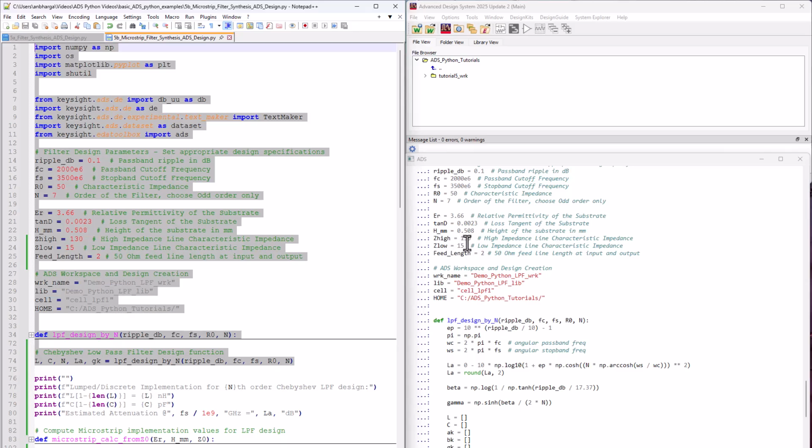So these two will put a constraint on what is the maximum inductance you can obtain, what is the maximum capacitance you can obtain, and based on that the length of the section will be determined. So you don't want to put any arbitrary number which cannot be fabricated in real life. So that we will take care of by putting these constraints here.